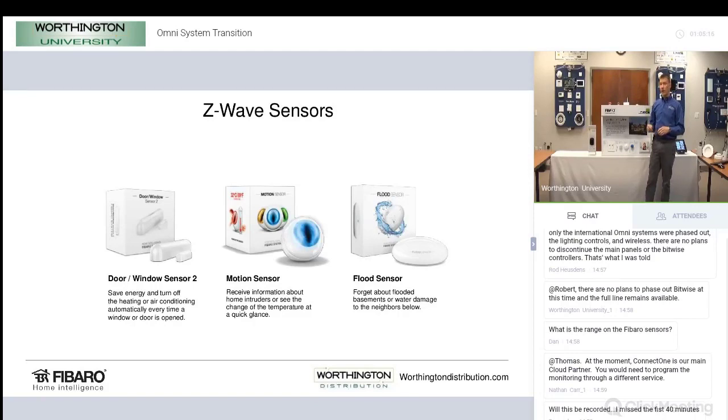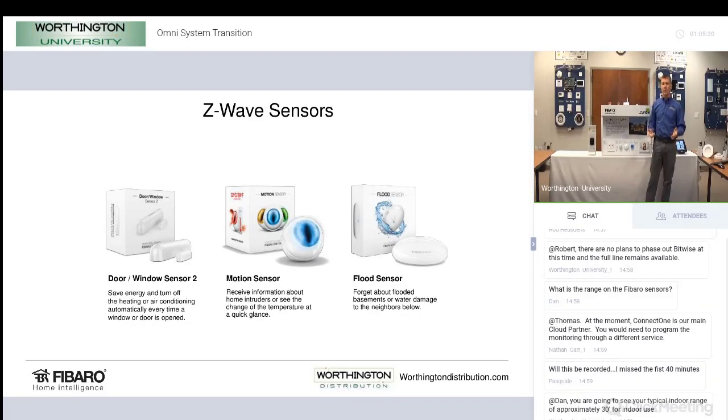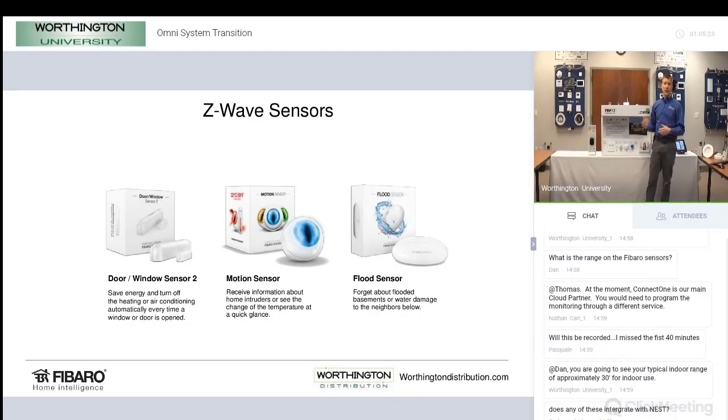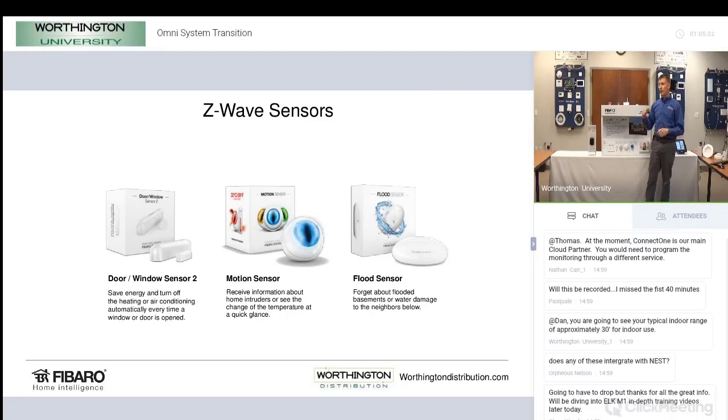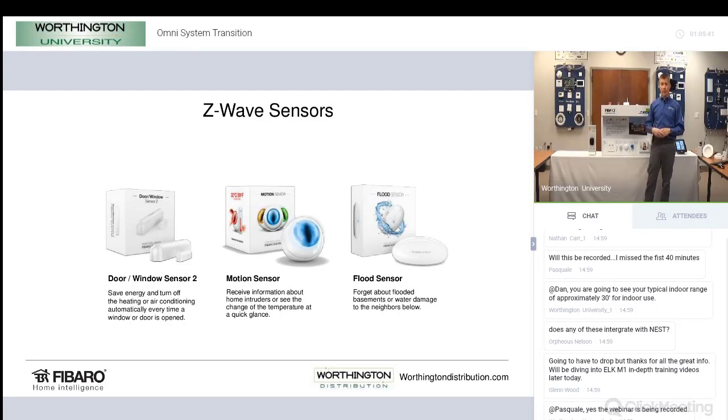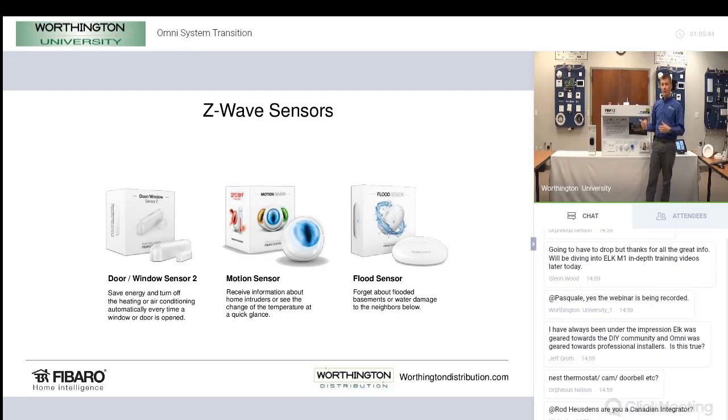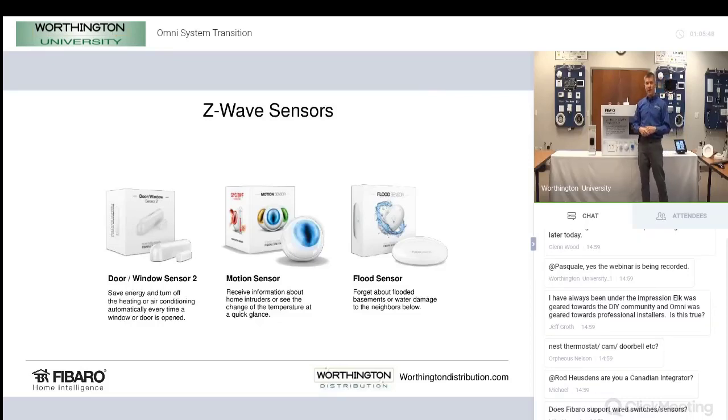That's number one. Number two, it is absolutely important that the flood sensor has a temperature sensor in it. And the reason for that is, for folks like us up here in the Northeast, we get winters that are just cold enough that we tend to see freeze-ups a lot in houses. So what happens up here is the house freezes because the furnace goes off for some reason, pipes freeze, and then when the pipes thaw, they're burst and we have a flood in the house. Well, we can detect that water and say, oh, you've got a problem, you have a big water mess in your house. But wouldn't it be nice if we could back up time on that a little bit and prevent that problem?